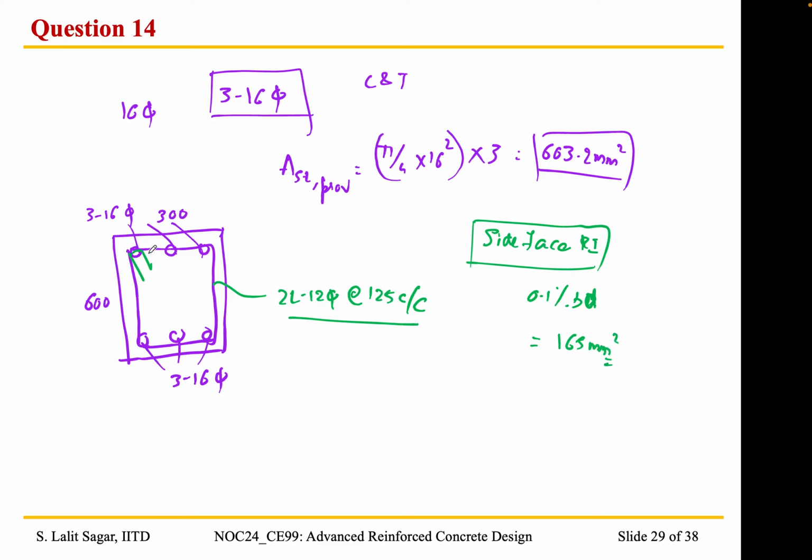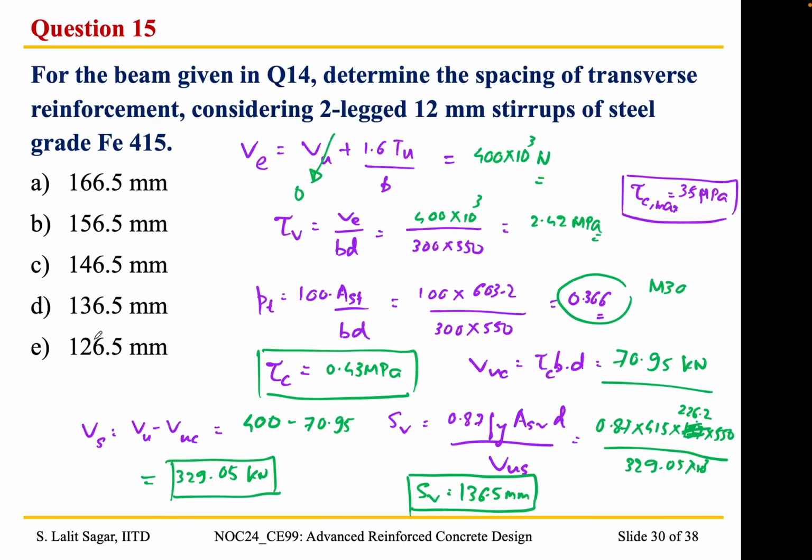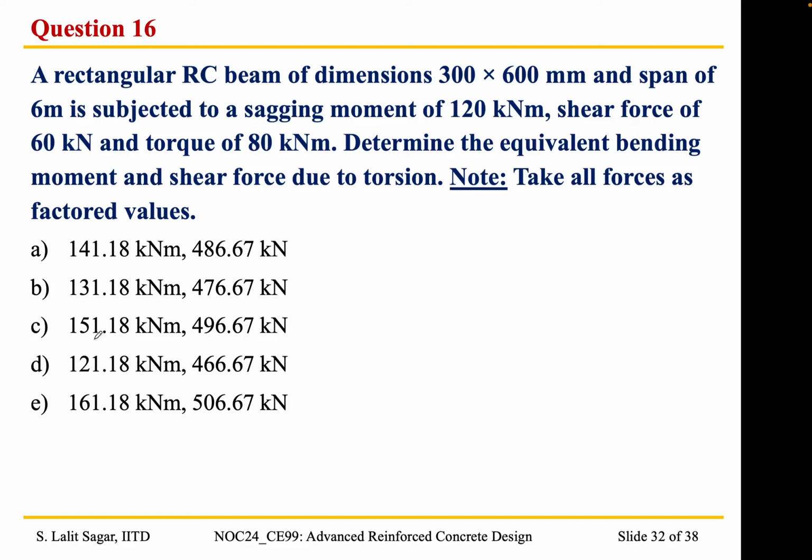So along with the longitudinal reinforcement for moment and for shear, we need to provide 4 bars of 8 mm diameter, so that will safeguard the beam against the torsion. Kindly make this addition also. So this will be 2 of 8 mm, and here we are going to provide another 2 bars of 8 mm. Sorry for the interruption, we can proceed with the question now.